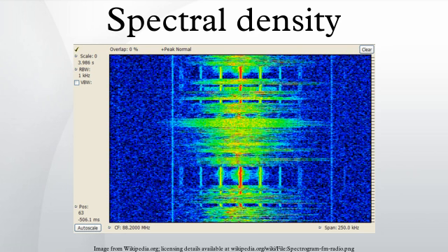Also, the wider the bandwidth that a spectrum analyzer possesses, the more costly it is, and the capability for more accurate measurements increases costs as well. The spectrum analyzer measures the magnitude of the short-time Fourier transform of an input signal. If the signal being analyzed can be considered a stationary process, the STFT is a good smoothed estimate of its power spectral density. These devices work in low frequencies and with small bandwidths. Coherence: see coherence for use of the cross-spectral density. See also: noise spectral density.